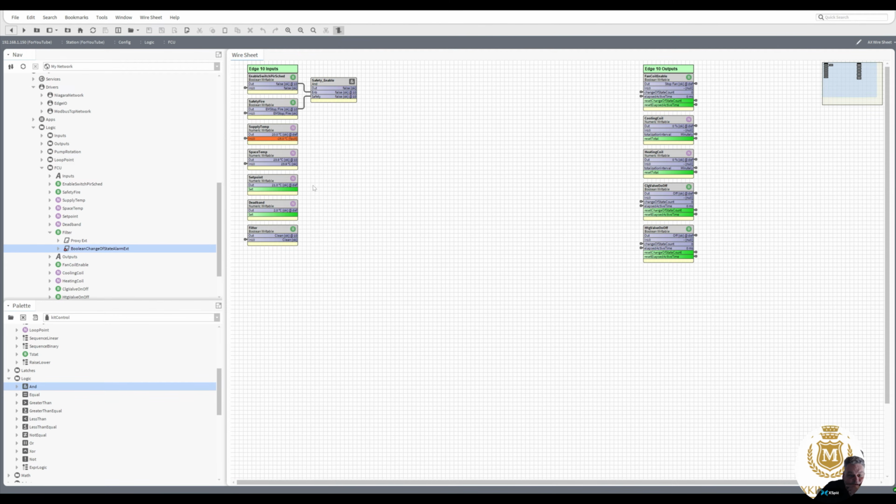So do we need to tie anything else into that? Not really. We don't want to put the filter in there. We still want the fan coil to run even if the filter is dirty. So we're not going to do anything with that point through the logic. So that's our output there.